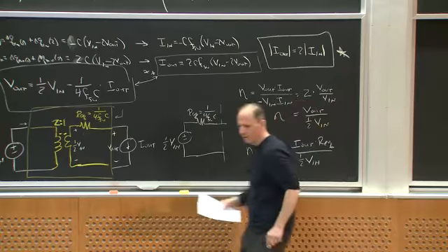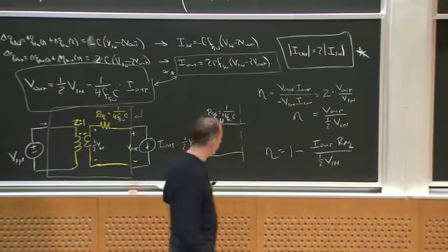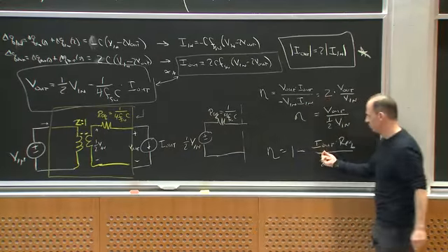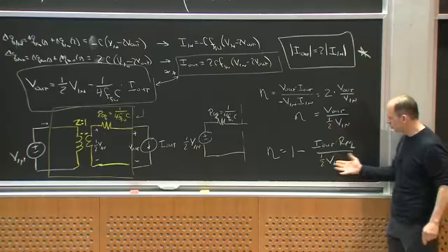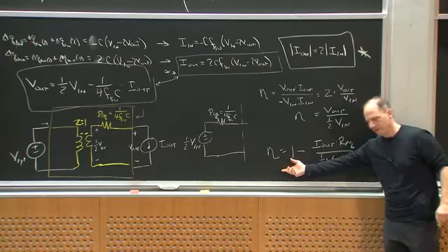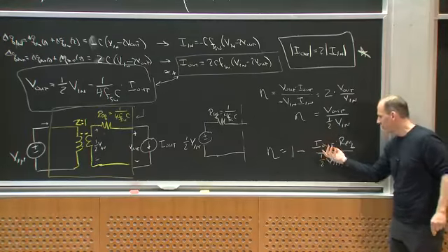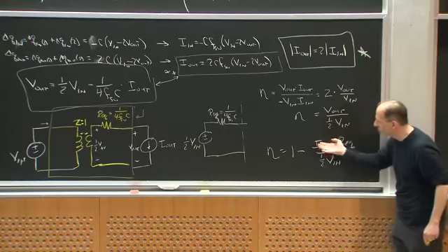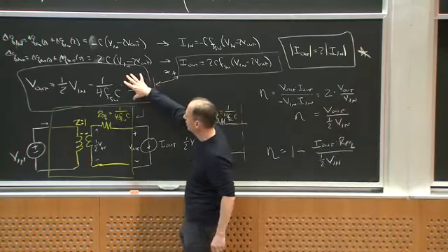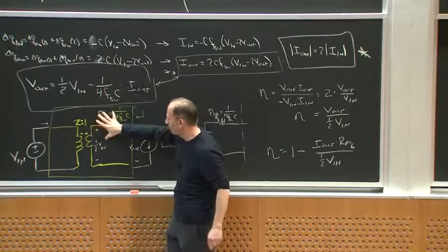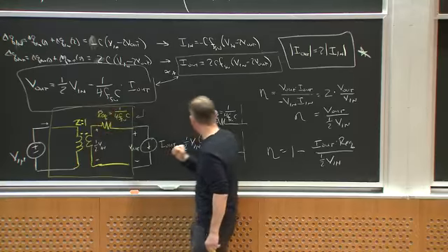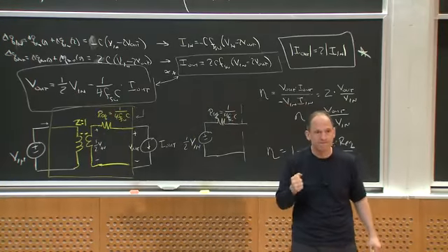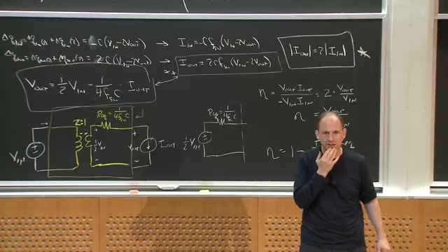Okay. This is just illustrating if my load current goes to 0, the efficiency then goes to 1. If my load current gets really big, the output droops down, right? As my output current gets really big, I get a bigger and bigger drop across this equivalent resistor, and my efficiency starts to decline. Does that make sense to everybody?